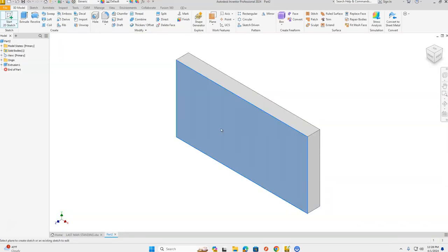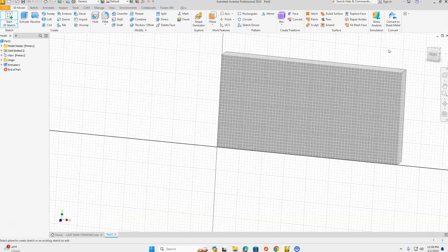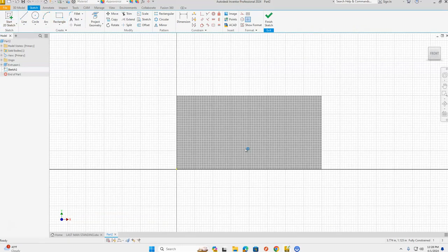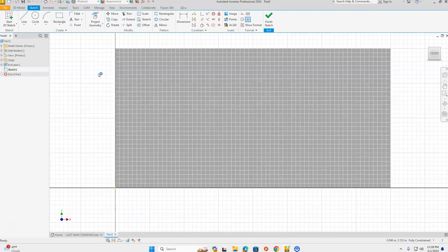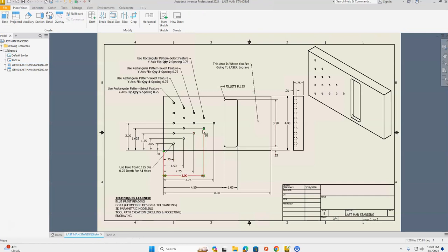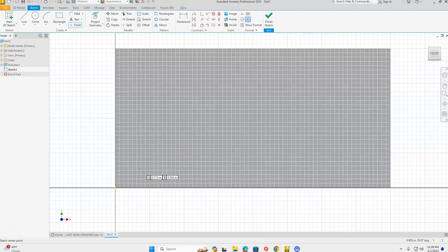let's take a 2D sketch, place it on our front view, and click Front in our world view cube so that it fits on our screen and centers it. And I'll just zoom in a little bit so we can see things. I'm going to get my point tool, and I need to have 1, 2, 3, 4, 5 points along that side. So let's start with that. Starting in the lower left hand corner, 1, 2, 3, 4, 5. See how I kind of have them going up at an angle? Okay, press the escape key, let go of your point tool, and let's take a look at our dimension.